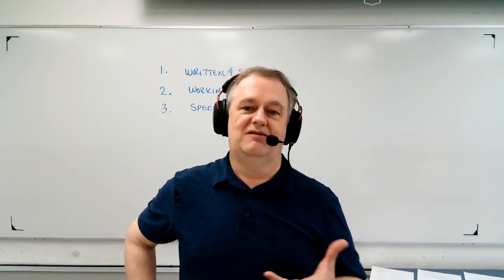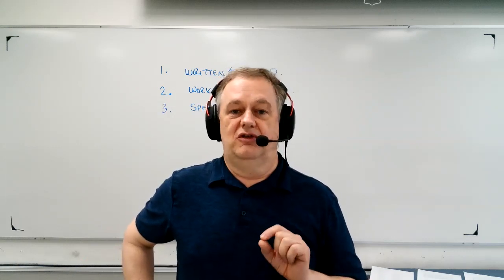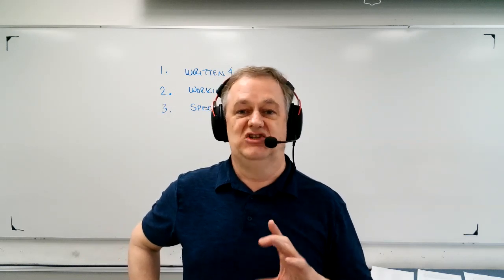So what I would say, and this is kind of a disclaimer, make sure that you investigate on the project that you're working on and make sure that you understand there's normally a legend that gives all the symbols and the specific references that you're going to need for that project. And it's very important to be aware of that, because not understanding and using a wrong component because you thought the symbol meant something else can be very, very costly and time consuming. So make yourself aware of what the actual legend is indicating on the set of plans that you're looking at.